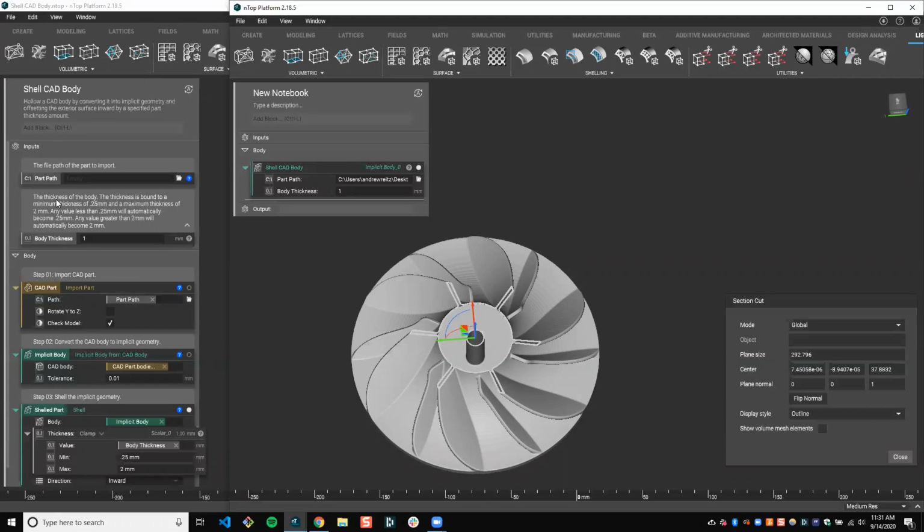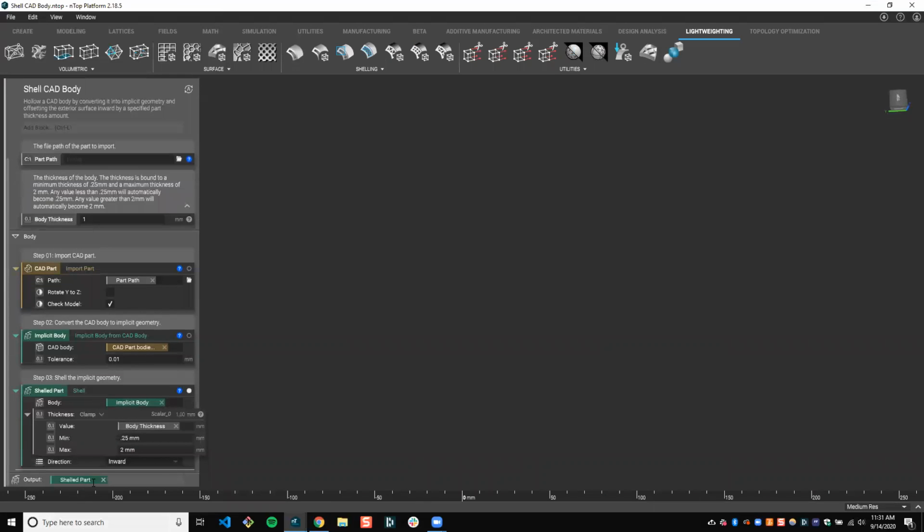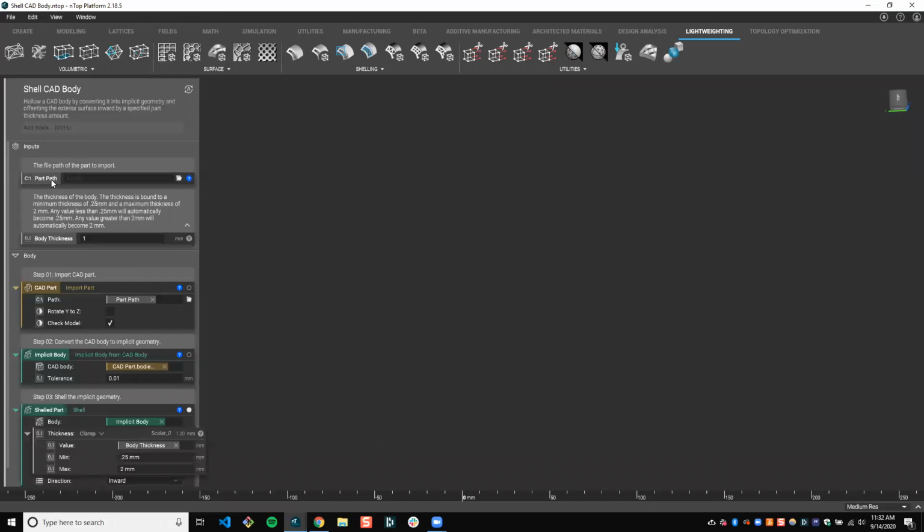We then set up some inputs. We went ahead and specified an output. We were cognizant of the order of the inputs. We also clearly labeled what the inputs do, so they have a description. We labeled our notebook, because the notebook name is also the custom block name. We gave the notebook a clear description, because this ultimately becomes the custom block description. And then we saved the file as the same name as our notebook.